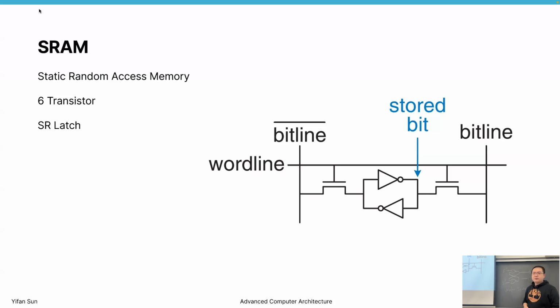Remember we said that for NVIDIA GPUs, 800 square millimeters is the largest one. But this one is probably tens of times larger, not really 100 times, but can hold at least 40, 80 of these types of chips. Now, how large is the memory on a wafer scale chip? I can tell you, on a wafer scale chip, they only use SRAM. In their second generation, they have 80 gigabytes of SRAM.